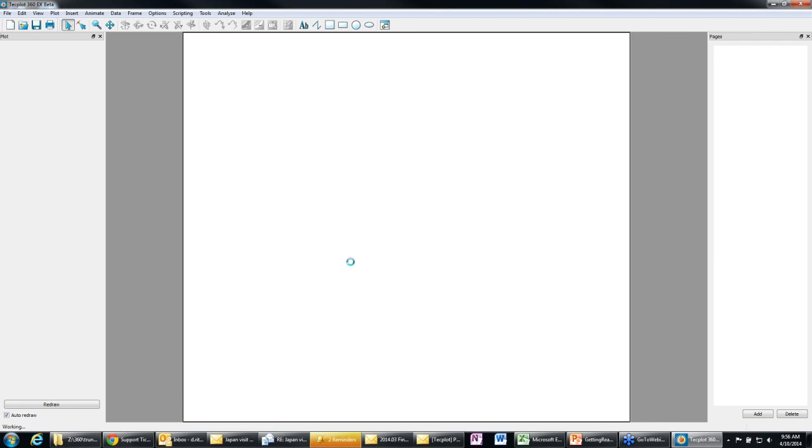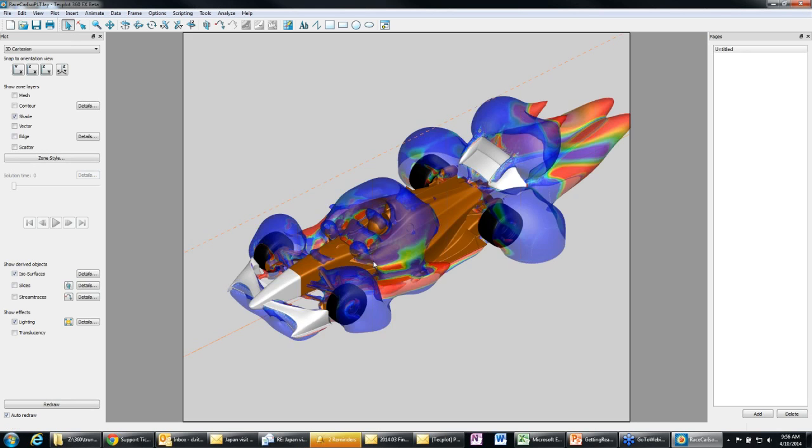So, the next one. You asked to show how to create stream traces over a 3D body. As he brings this up, he can show you how to do that. Oh, this is an ISO surface. So you can basically click on those ISO surfaces and seed stream traces.